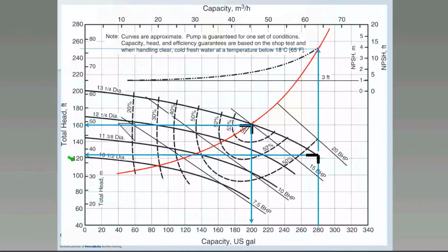So one thing that we need to note here is that we have moved a long way to the right of the pump vendor's curve. And this can introduce a lot of other problems. We've not only increased the horsepower on each pump, we have also reduced the operating efficiency. And when we move this far to the right of the vendor's pump curve, we start to put a lot of additional load on bearings, increases in vibration. We see potential damage for seals, that kind of thing.